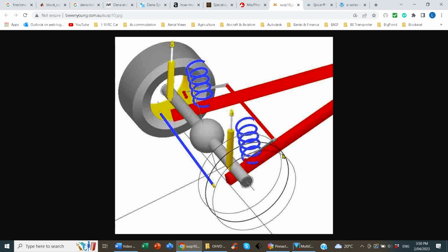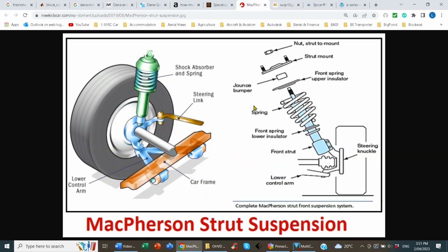If this is a front axle, these two members would be leading arms. If this was a rear axle, these two would be trailing arms. If you look under a Range Rover or Land Cruiser, you'll probably find it has leading arms and trailing arms. And there are other links required as well, but that's the basic arrangement. And popularized by smaller Japanese cars, a McPherson strut, a coil spring wrapped around a shock absorber. Interestingly, this spring is actually shown as progressive, so that's great.